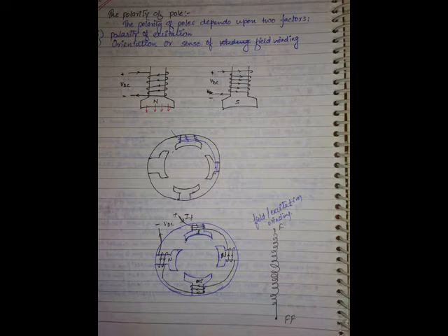Without heating of the machine, you won't get anything. It may be any loss: copper loss, eddy current loss, hysteresis, mechanical, frictional, any loss. The final form is temperature rise. Energy cannot be created nor destroyed. This temperature rise is some part of energy lost out of the input.